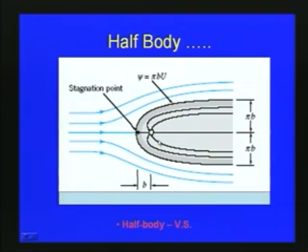So here this is just like a solid surface, this closed streamline here. That is why it is called a half body, and then you can see that there is a point where the velocity will be 0. That point is called the stagnation point, and so on the surface of this half body, psi is equal to pi b U, where pi b is defined as the width of this half body with respect to both directions, both upward and downward.